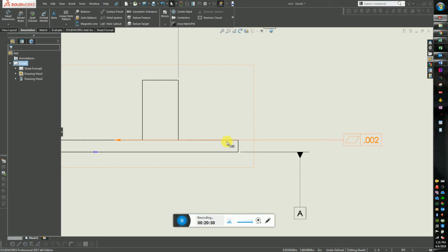Generally speaking, any ground plate that you're going to get is going to be flat within 5/10,000ths of an inch. So not too much to worry about, well, depending on the material. If you have a piece of flame cut plate that's going to be wavier than all hell, that would be an example of where you could use a flatness callout.